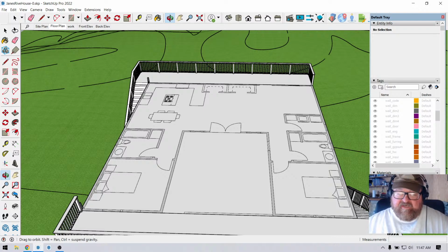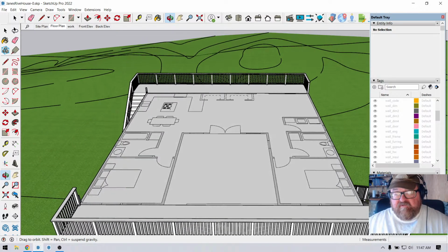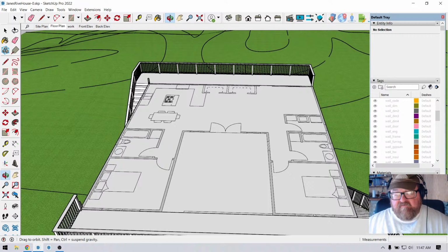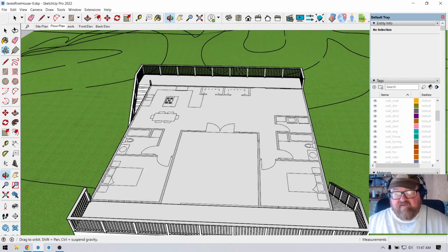They put a slight camber to a roof truss, and then by the time you put your roof decking on, it'll sit down on these interior walls. But there's no real load. In other words, you could take out all these interior walls and roof trusses would span the whole thing. But the reason I'm bringing this up is because she was talking about vaulting the porch area.